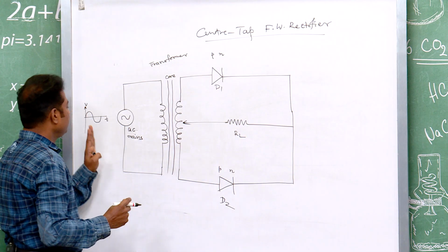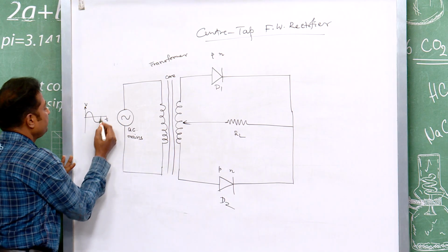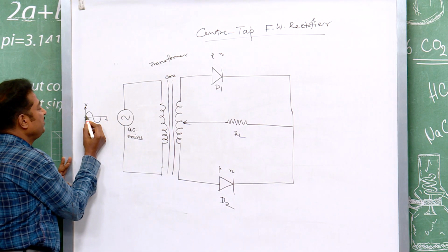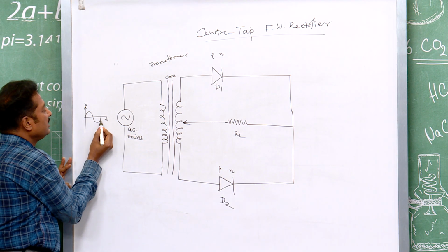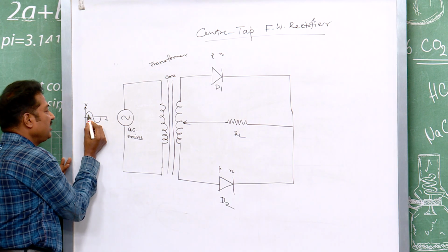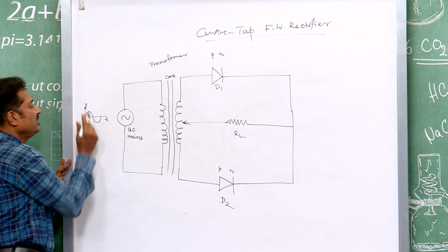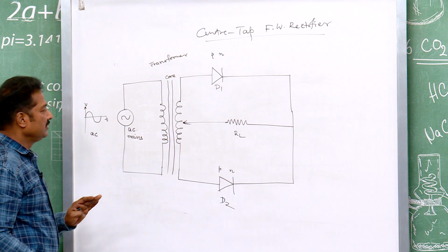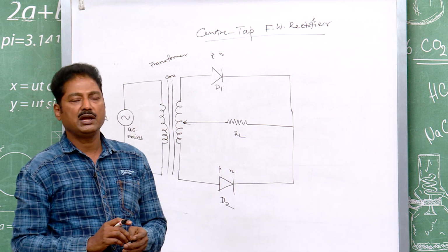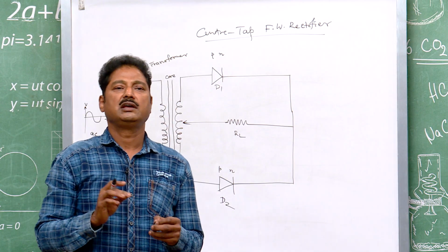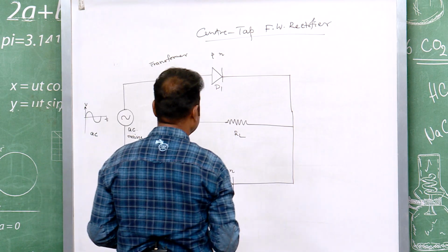Now, similarly, a similar explanation, the AC means it gives you AC in this pattern, the voltage will be in this pattern, means it will be increasing, going to maximum, then decreasing to 0, then increasing, then decreasing. Suppose it is from left to right, it will be right to left. It is positive negative, it will be negative positive. So, this is what the AC signal is. We have to find the signal at the output end. At the output end, that will be DC, means its magnitude will be constant, its direction will be constant, one directional.